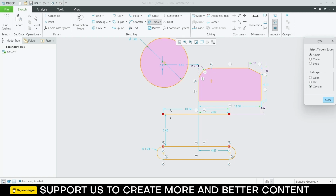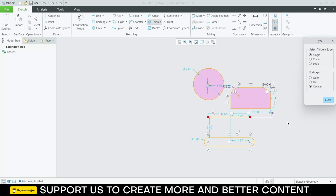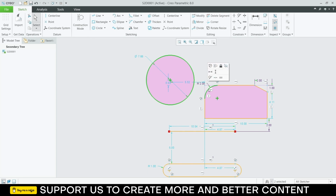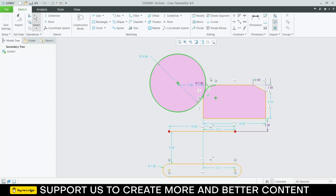Okay, you can try out many other things as per your requirement. Now let's try to understand something called constraints. Constraints are very important. For example, I want this circle to just touch this arc. How can I do it? First close this. By pressing Ctrl, select this one and this one. Click on tangent. Notice it is now tangent to it. I have added a relation.